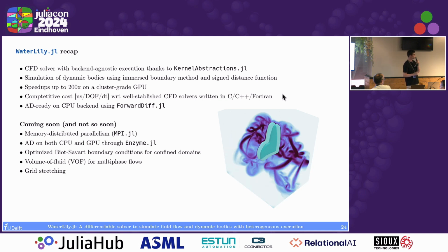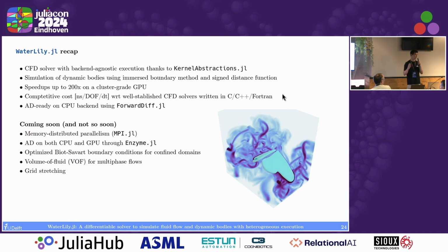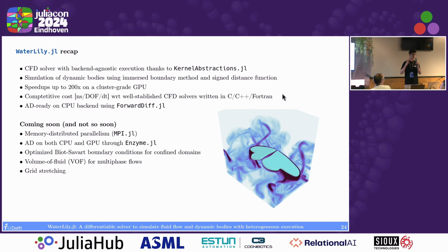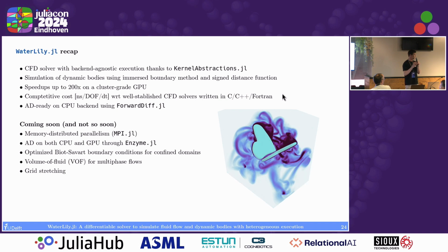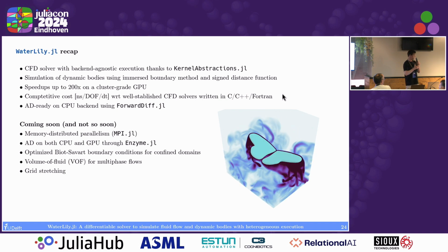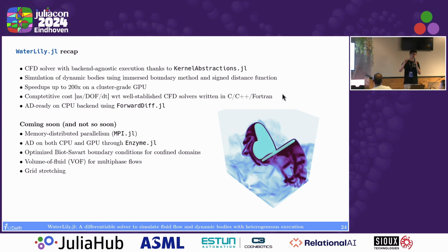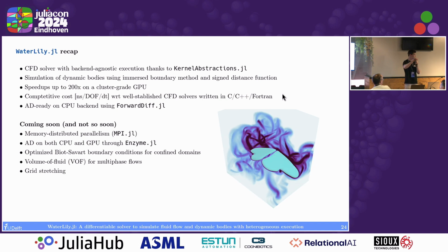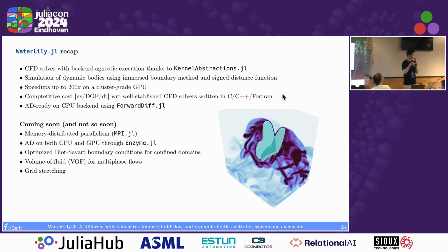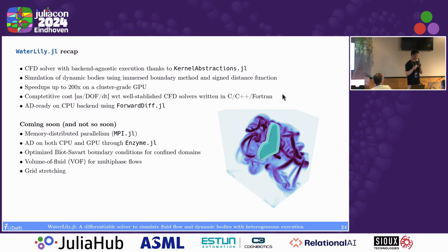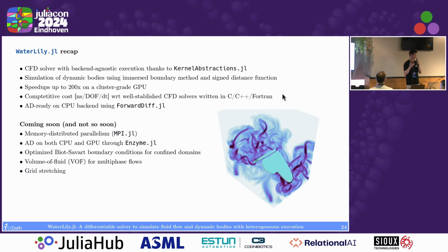There are a couple of ways to fix this. One is to have a formulation that allows a very fitted or confined domain close to the body, which still produces a physical solution. This is through the Biot-Savart boundary condition, which is a prediction of the velocity on the ghost points of our domain, much better than the typical predictions you get from a convective outlet, for example.